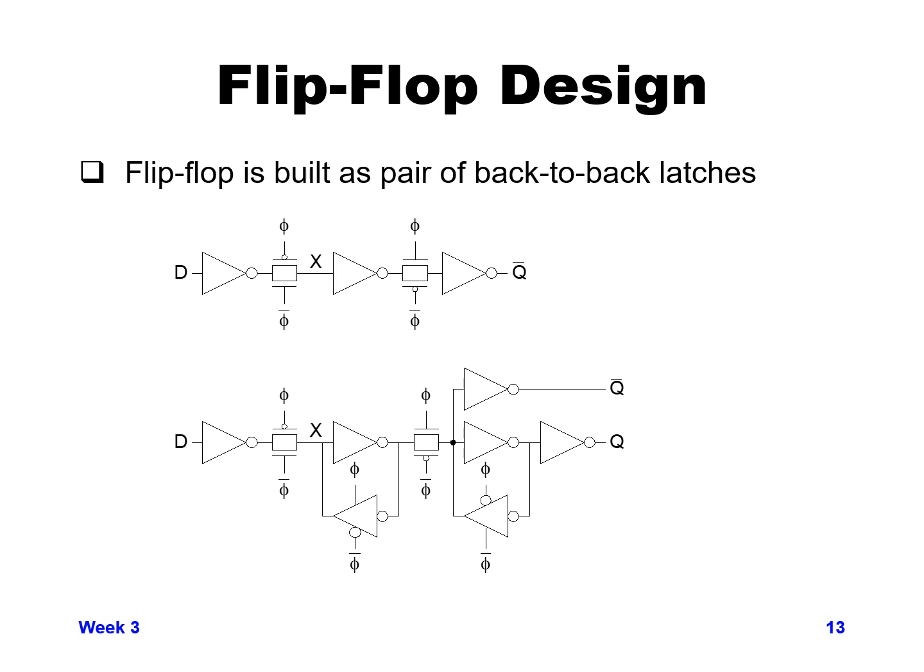So as we can see here, starting, you could say this is a buffered latch with inverter, pass gate, inverter, followed by an unbuffered latch where it's just pass gate, inverter for the top design there.